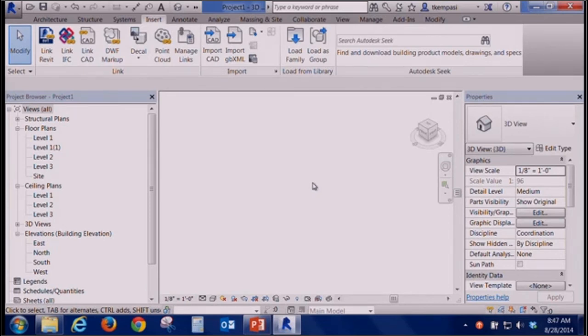The geometry. You're going to have the best success working with geometry that comes from other Autodesk applications, obviously. What I was trying to show with the SketchUp file is it treats it as a solid element. It doesn't treat it necessarily as a building, and when you cut a section through it, it just shows an elevation of it.